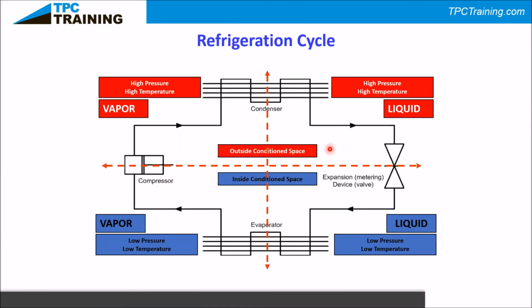The reason we have a flooded market with all kinds of new refrigerants out there is because on January 1st of 2020, R22 ceased to be produced in the United States of America. So they're scrambling, trying to find a replacement for it because the cost is astronomical. It's going up. And Brian, you're familiar with that. You had a system which was low on refrigerant, and you had to add R22. So there is what we call a SNAP list out there. ASHRAE has put together a SNAP list to help customers and technicians know whether the refrigerant is approved by the Refrigeration Association, saying, yes, this is an acceptable replacement.